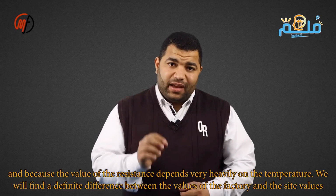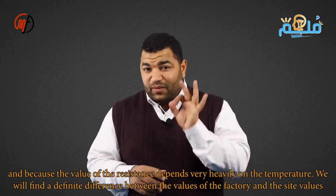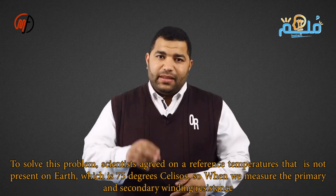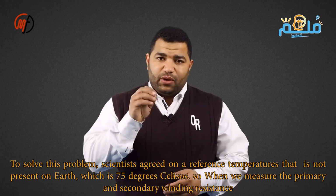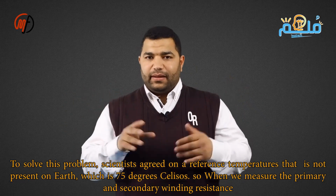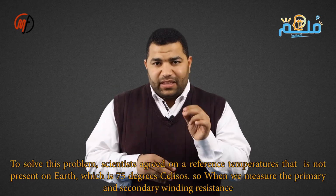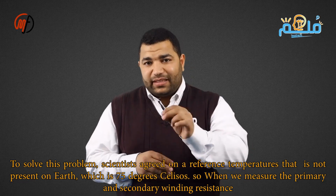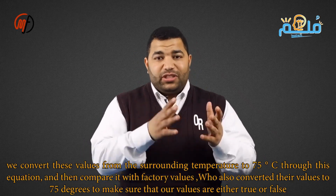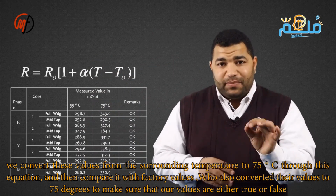Since the resistance value is sensitive to temperature, we will find a difference between the factory and site values. To solve this problem, a reference temperature of 75 degrees Celsius is used. When measuring primary and secondary, we convert these values from ambient temperature to 75 degrees C and compare them with factory values, also converted to 75 degrees C, to verify accuracy.